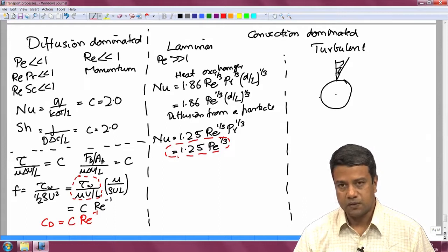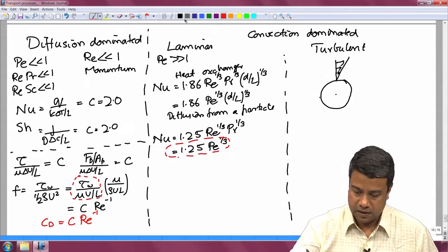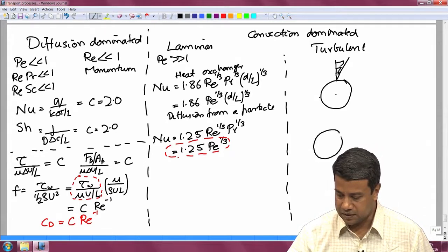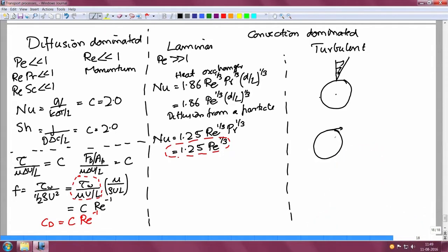I could have, for example, a gas bubble. A gas bubble does not afford resistance to flow. So, at the bubble surface itself, the surface can have a tangential velocity. It cannot have a velocity perpendicular to the surface because there can be no penetration if you are moving in the reference frame of the bubble itself, but it can have a tangential velocity. The details of the velocity very close to the surface are important, because the concentration or the temperature difference is restricted to a thin region near the surface, and the details of the velocity in those thin regions is important for determining the transport rates.